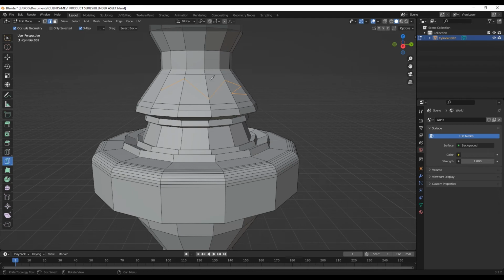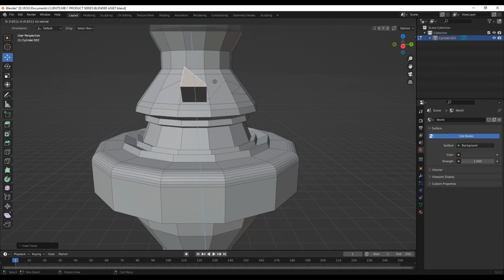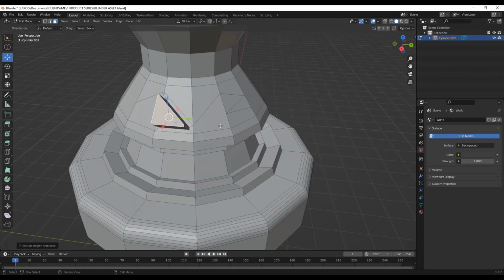So note that as you've made this cut here, it means you've created unique sets of edges and faces. So if you go to our face mode now and let's go to our move tool, you see now that if you select this face, because of the cut we've made, you can now perform unique actions on these particular faces. So you can also inset the face here. If this is what you want to do, you can extrude this. You can do other things.